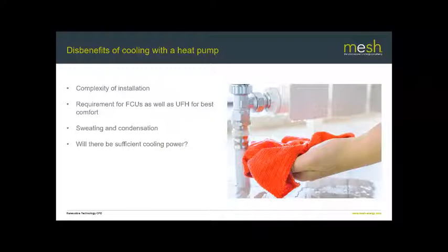Will there be sufficient power from the heat pump to provide all the cooling necessary? Often we find that cooling loads are significantly higher than the space heating loads for a building, and usually heat pumps are specified with the peak heating demand in mind. Therefore, it may be that additional cooling power is required to supplement that provided by the heat pump.